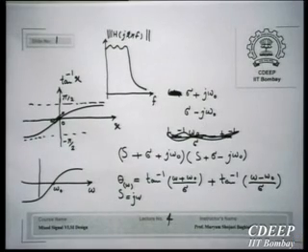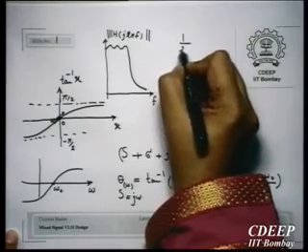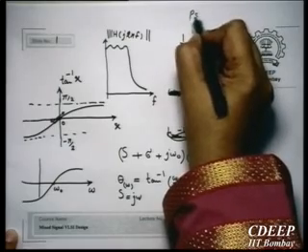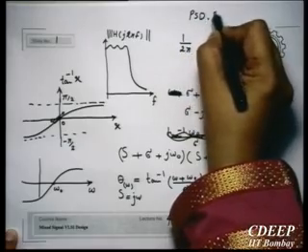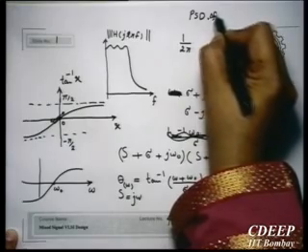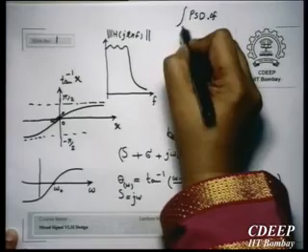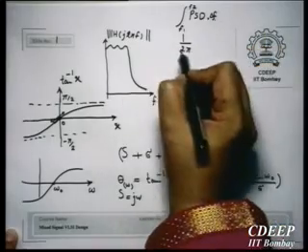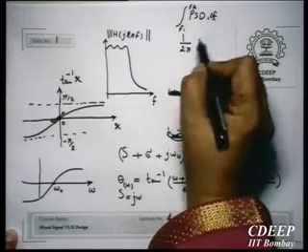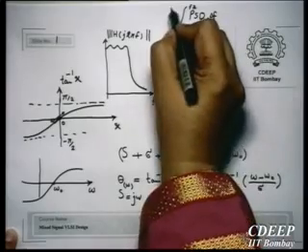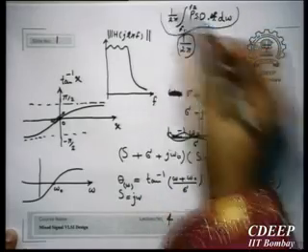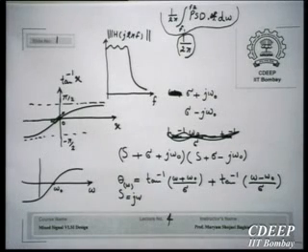And there was a factor of 1 upon 2 pi in the first lecture, one of the students mentioned. So please correct it in the calculation of noise, because noise power spectral density is a function of f. We multiply it by bandwidth and then we integrate it from some frequency f1 to f2. So this is f. Therefore, in the relation I had written in the first lecture, I used omega, so you add a coefficient of 1 upon 2 pi to the integration. And here you will have the omega. These are just two things I wanted to mention so that it will be clear.